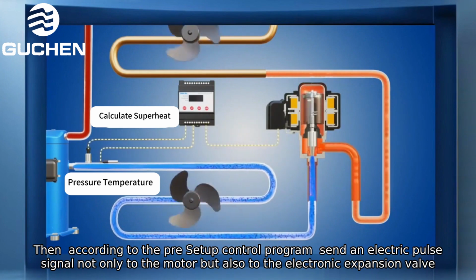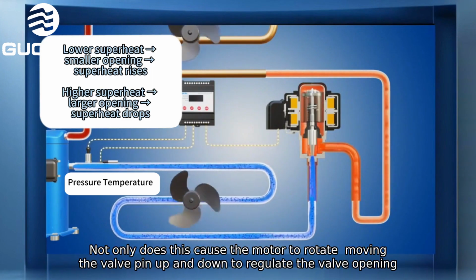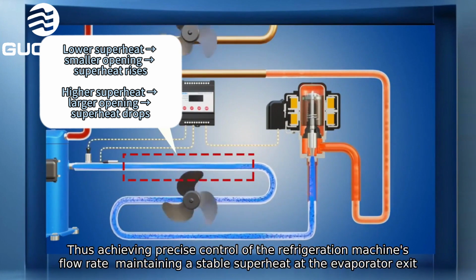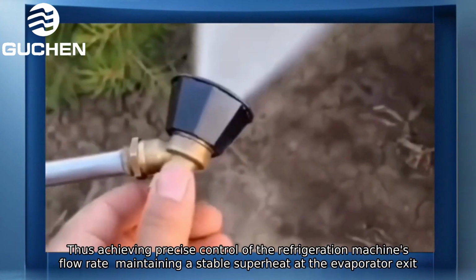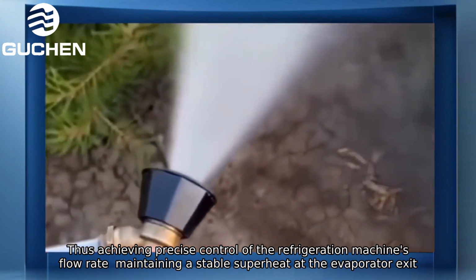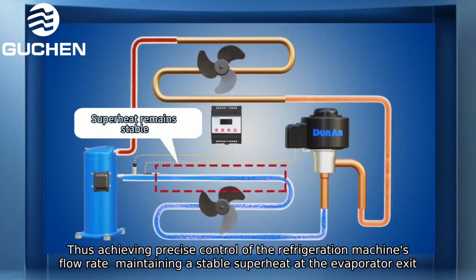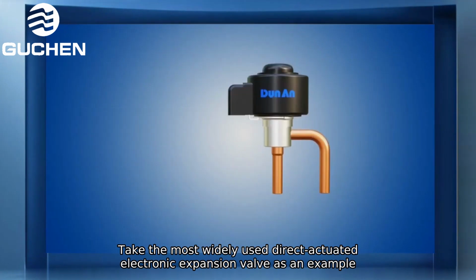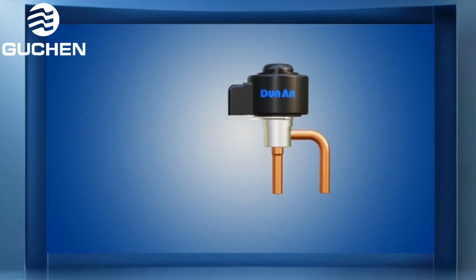to the electronic expansion valve. This causes the motor to rotate, moving the valve pin up and down to regulate the valve opening, thus achieving precise control of the refrigerant flow rate and maintaining a stable superheat at the evaporator exit. Take the most widely used direct-acting electronic expansion valve as an example.